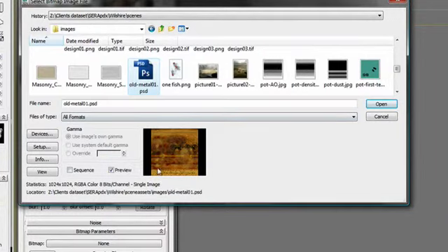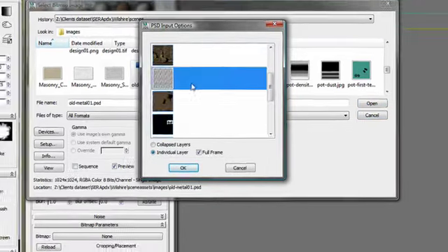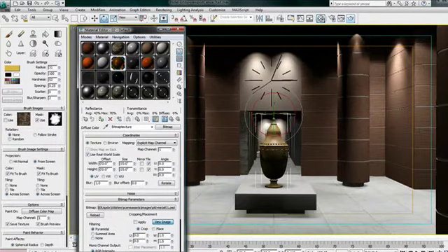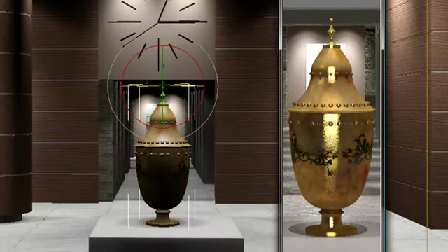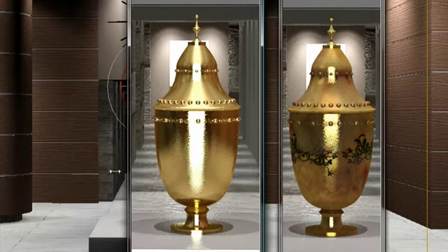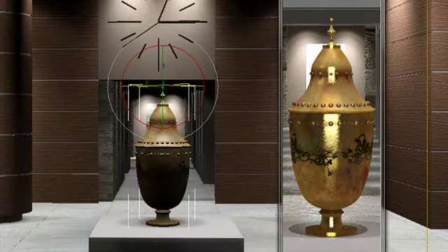For a more accurate bump map, you can choose to load a layer from your PSD file that will match your diffuse channel. Let's render the result and see if it is closer to what I am looking for. The decorative vase now has more of an aged look, which is what I am looking for. You will love adding realism to your texture, making your texture exclusive for each project, adding character and personality to your project with the expanded toolset for 3D painting.